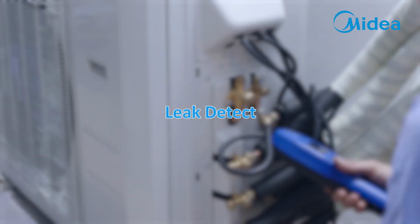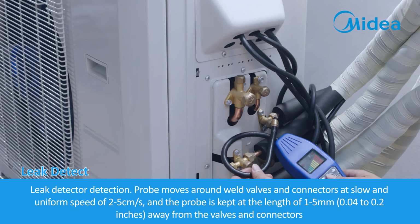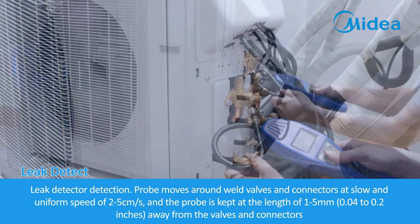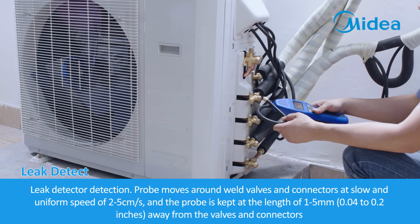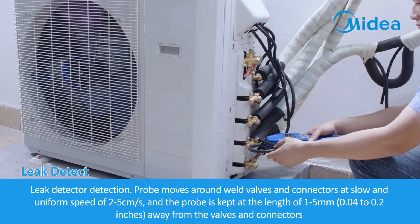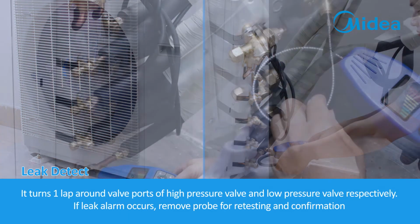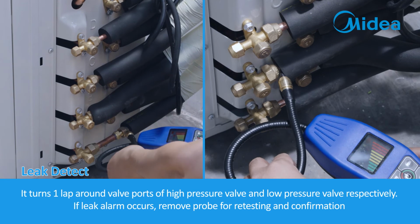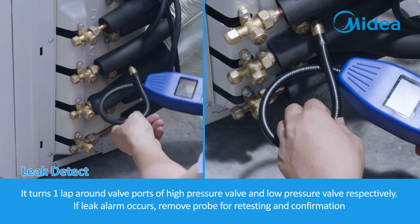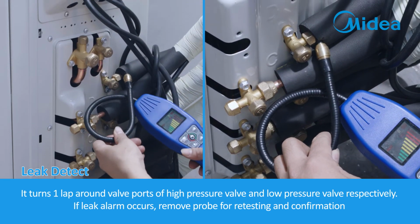Leak detect. Leak detector detection. Probe moves around weld junction at slow and uniform speed of 2 to 5 centimeters a second, and the probe is kept at the length of 1 to 5 millimeters, 0.04 to 0.2 inches, away from the valves and connectors. It turns one lap around the valve ports of high pressure valve and low pressure valve respectively. If leak alarm occurs, remove probe for retesting and confirmation.